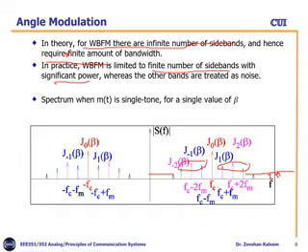So in practice, wideband FM is limited to a finite number of sidebands. So here we have three with significant power. We call them significant because the other bands are treated as noise, since they are below the noise figure, right? Below the noise limited power. So we can't differentiate between the noise and the sidebands.